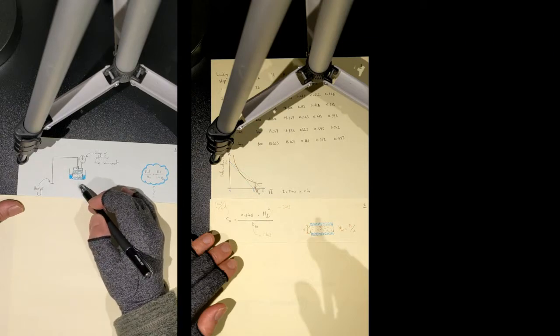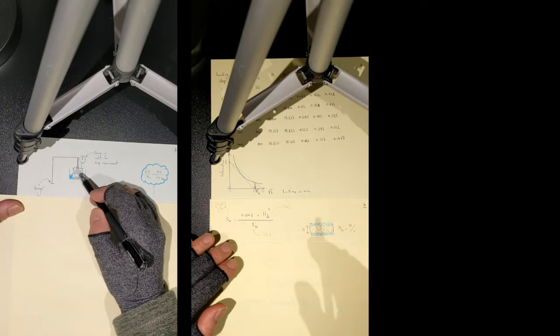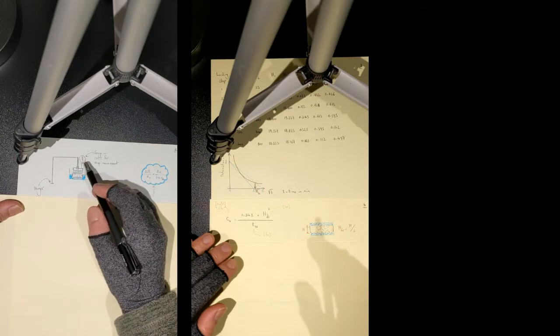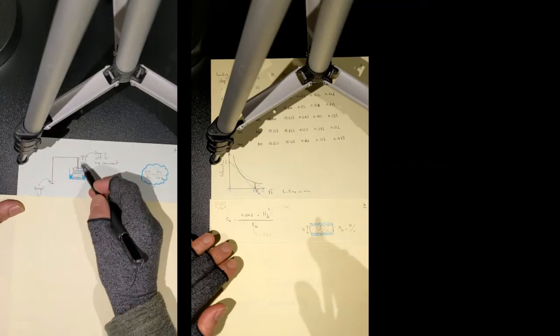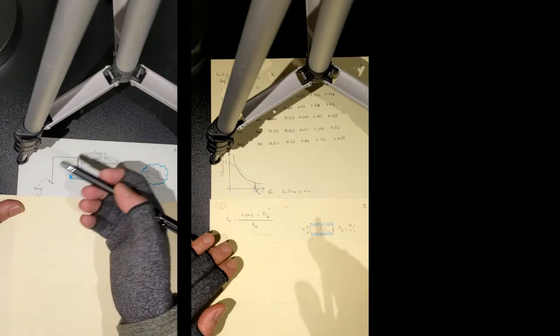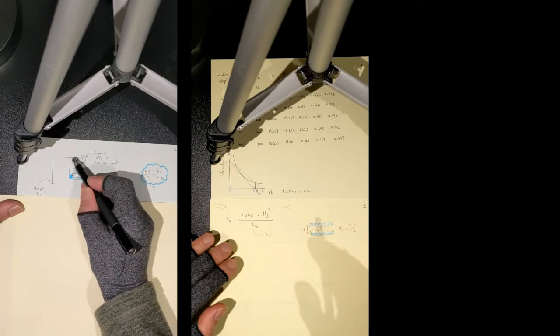You may have a ball to make sure that the load that applies to the soil specimen is definitely central, or you may not. And there are different loading frames, but the traditional loading frame has a rod on top, and this rod continues with a kind of horizontal lever, which is connected to a hanger.